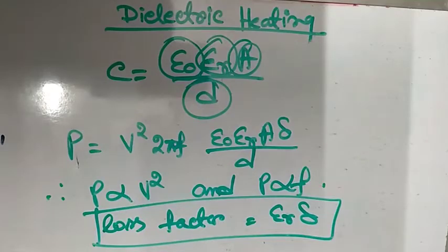For maximum power transfer, the output impedance of the source of frequency must be equal to the impedance of the inter-electrode, which keeps on changing with change in frequency. The impedance of the workpiece also changes with the change in mass of the same material or different materials having the same mass. There is a fixed frequency for a particular workpiece when for a particular voltage the power transfer can be maximum. It is practically not possible to have different generators for different workpieces.